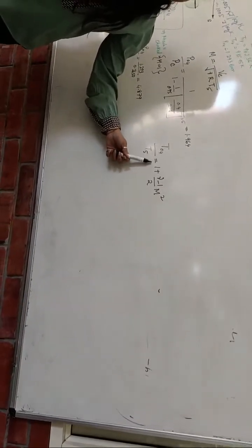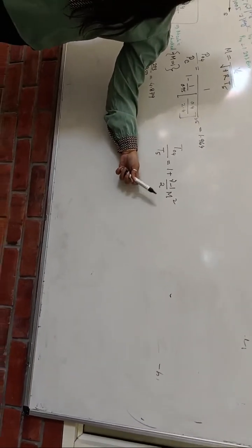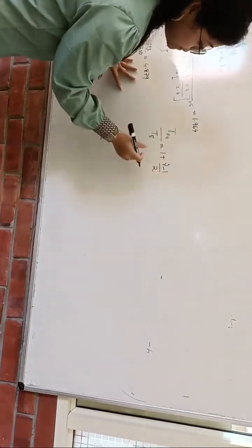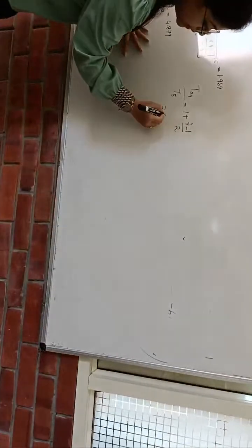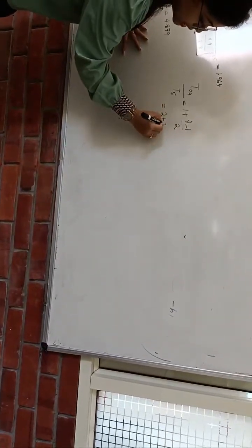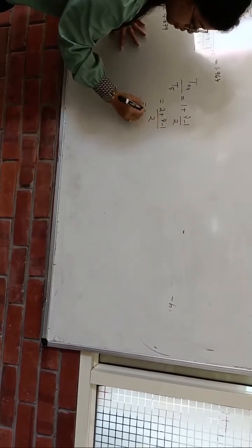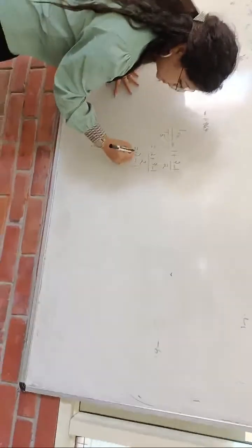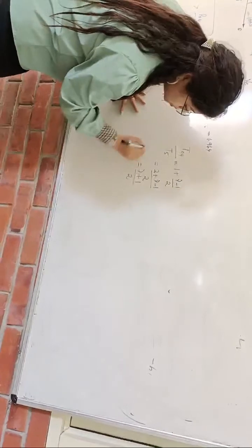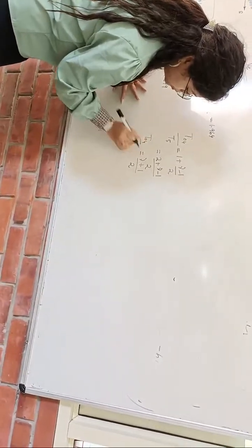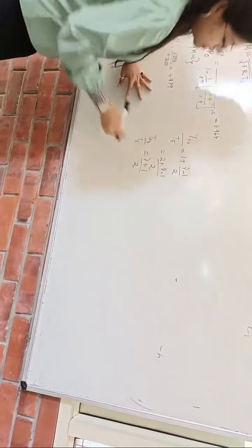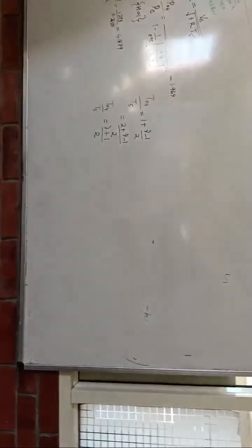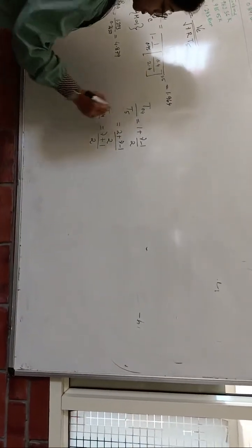So now, as the Mach number is 1, because the nozzle is choked, if I substitute here, what I will get: 2 plus gamma minus 1 by 2. If I rearrange this equation, I will get gamma plus 1 by 2. So T04 by T5 is gamma plus 1 by 2. Now T04 is known to you.